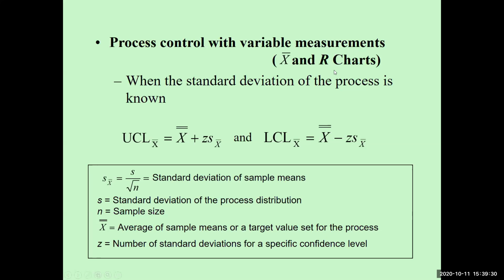X bar and R chart. If data is variable, numbers, like volume, heights, lengths, and so on, then we can draw X bar and R chart using this formula.